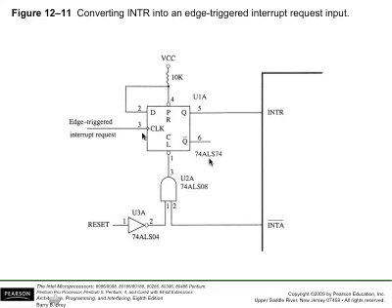So we're going to have a 0 output on the Q. When the edge trigger happens, because this is a clock pulse, this value of 1 will be updated to Q, and that's how we generate an interrupt.